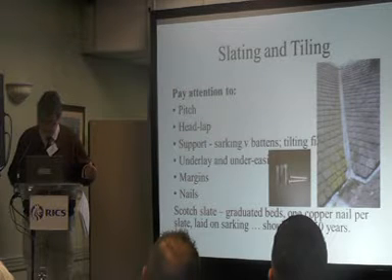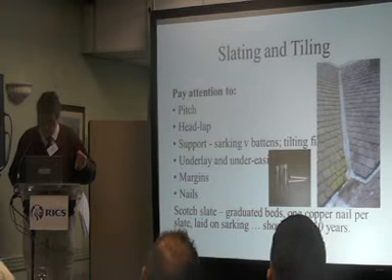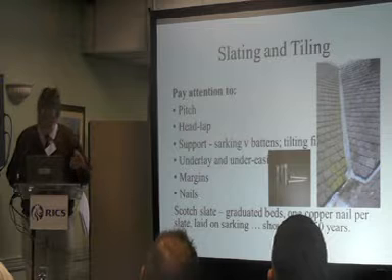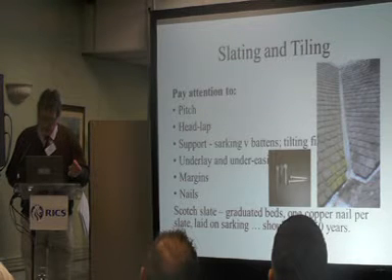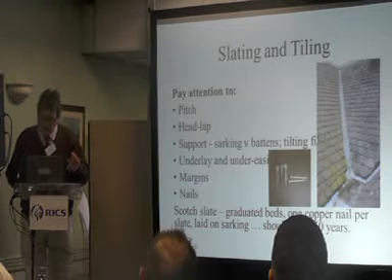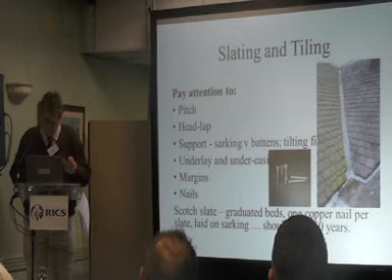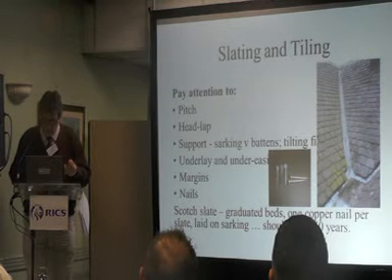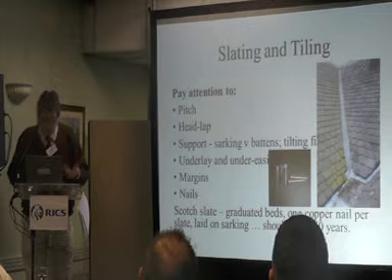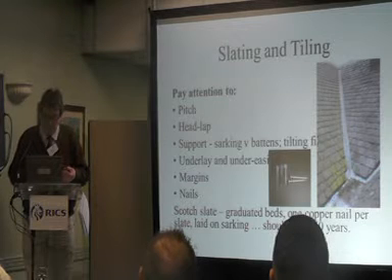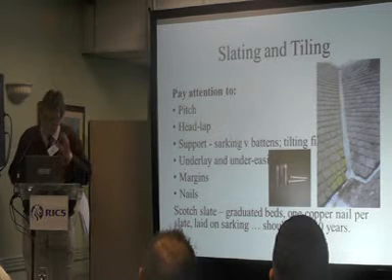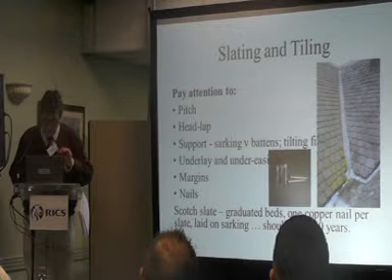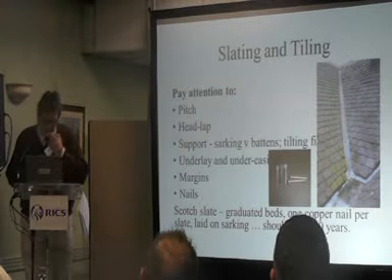Headlap. If you are working on a lower pitch, you need to increase the headlap. Support. In Scotland, of course, we're used to sarking, fully sarked roofs, and we do less on tiling battens. And I'm English, but I think the Scottish roof is just the most wonderful structure. It's very, very, very well built, and I'm going to talk in a minute about Scotch slate.